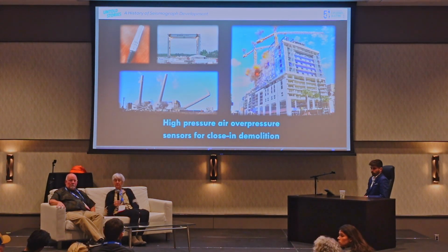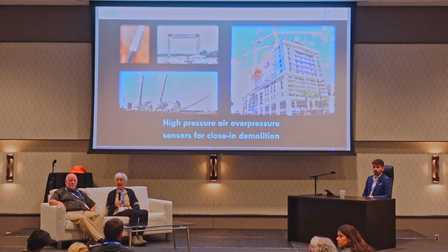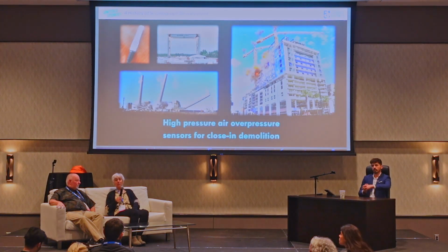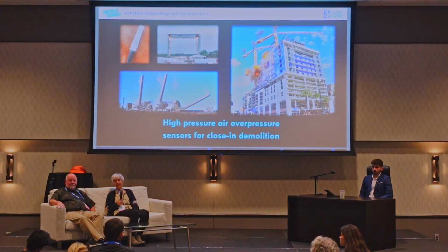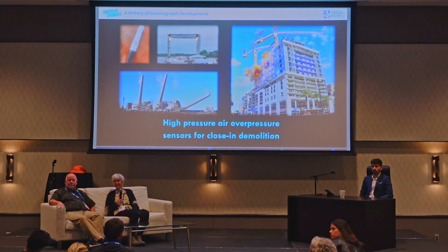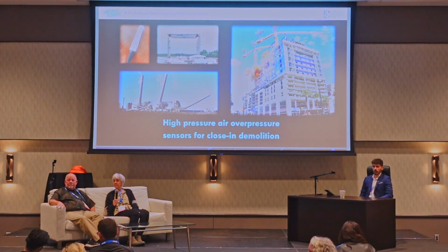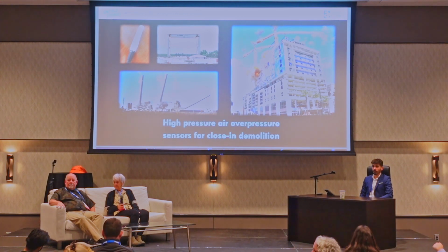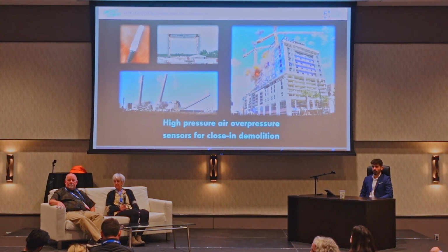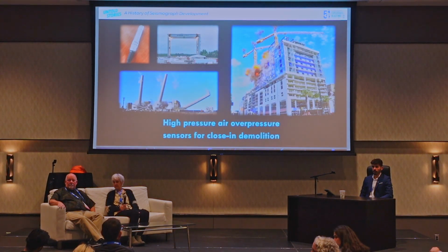So do you foresee some changes in the regulations that are currently at 132 or less? It'd be nice, but I think the human response is going to keep that low, unfortunately. Yeah. But that's a good question. So on demolition in the past 5 years, the lowest that I've witnessed a breakage of glass is 163. Oh my goodness, is it old glass? It was old single pane glass. Yep. And then I did see a cracked pane fall out at 156.